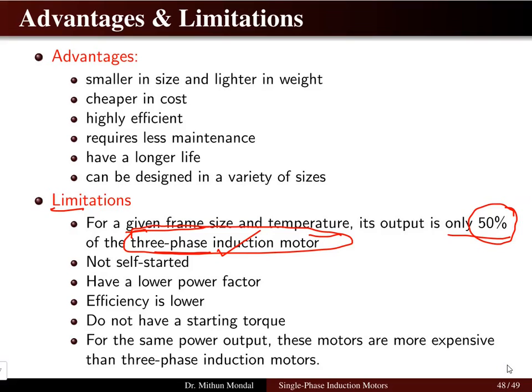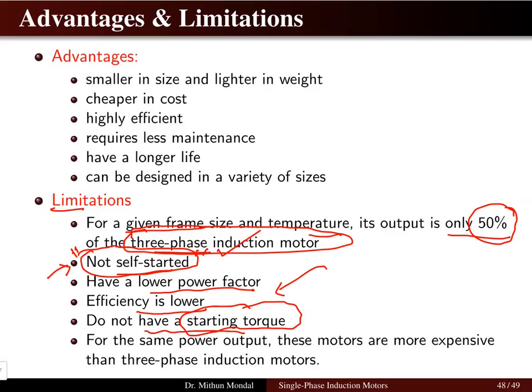It is not self-starting. We have seen this in the previous lecture also, how to make the single-phase induction motor self-starting using the auxiliary winding. So single-phase induction motors are not self-starting. It has a very poor power factor and lower efficiency, and does not have a starting torque. So we don't have any starting torque. An extra winding or extra connection is required to start the motor. For the same power output, these motors are more expensive than the three-phase induction motor.